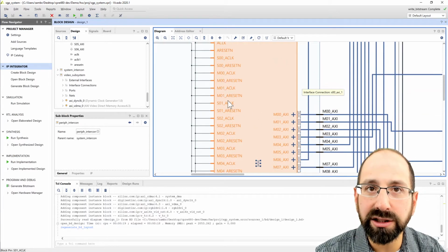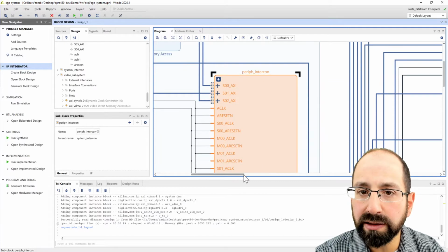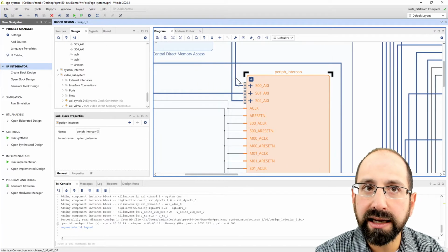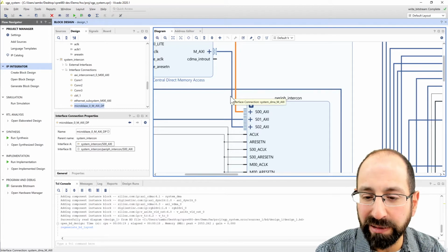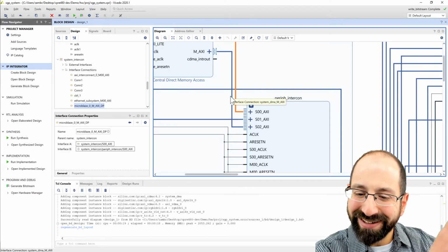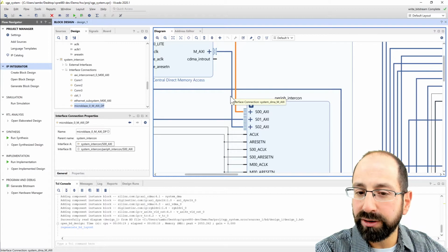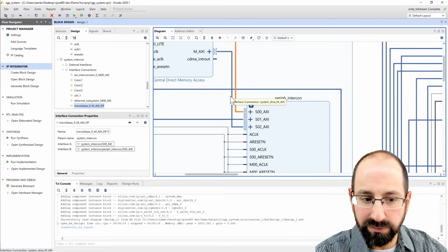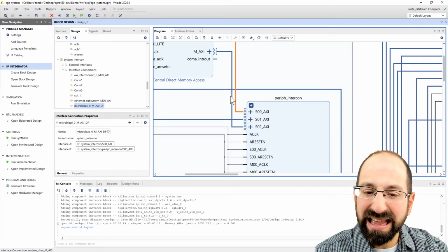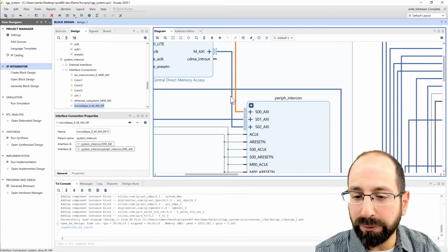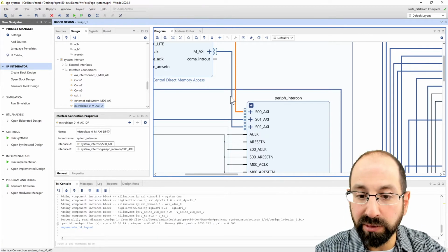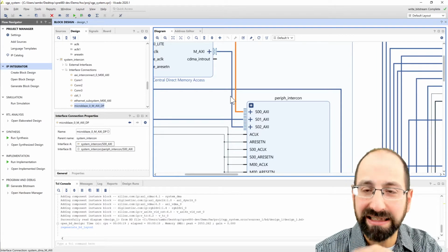In terms of the masters, you're not actually using too many of them this semester. The first one is going to connect to the Ethernet subsystem. That's where the driver is going to come in, right? OpenGL code triggers calls in our driver. It's going to trigger Ethernet UDP packet sends. That's going to wind up on that highlighted wire there. That's what's going to allow us to configure and read status from all of the cores in our system that are connected to this interconnect.